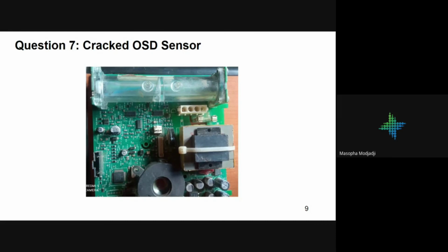Luckily, most of the time, these cracks form from the inside, and the seals within the sensor are still maintained. But it is important to verify that there is no leakage with some soapy water. Be very careful when checking the leak, as you do not want to cause any short circuit with the water. So this is something you should not worry much about, but you need to keep a close eye just in case the crack grows. Thank you, Moi.